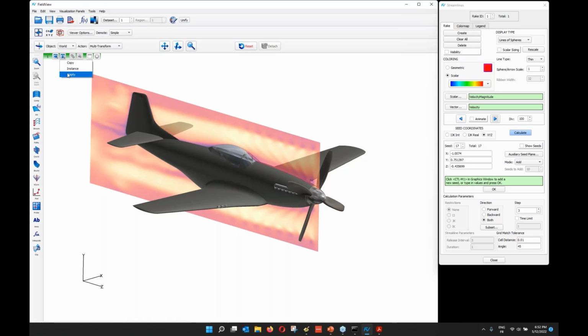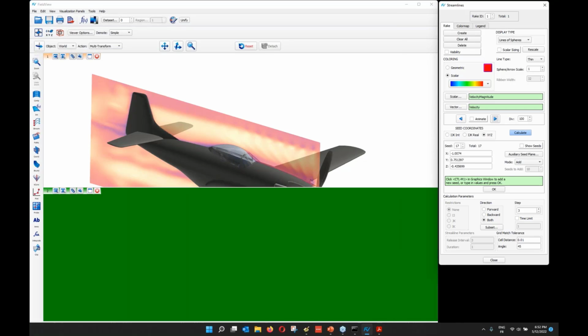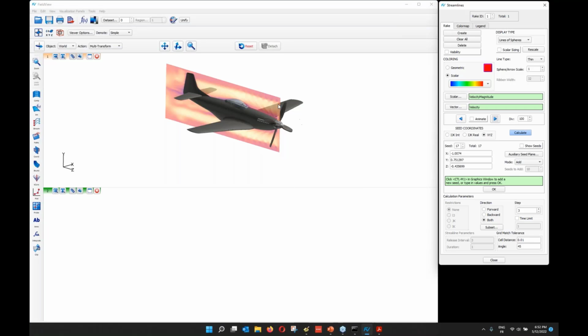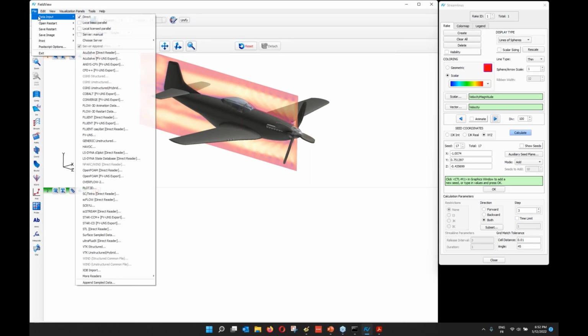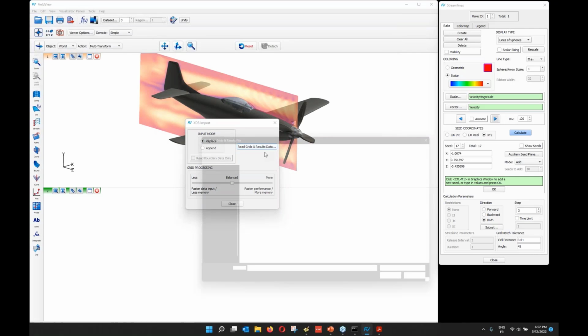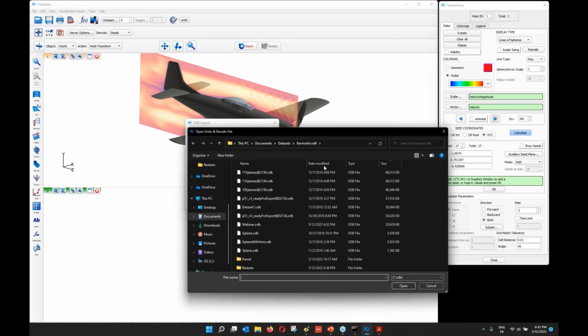Before I load it, I want to create an empty window over here. This is where I'll put what I've just exported, to not touch what I have in my session at the top. So from the bottom, we'll do file. For the format we've just used, we want to read it in serial because that's a small case. This is the import for the format we've just exported. Again, it's called XDB. Go and load that. The file we just created together, webinar.xdb, is just above 20 megabytes compared to 1 gigabyte again.